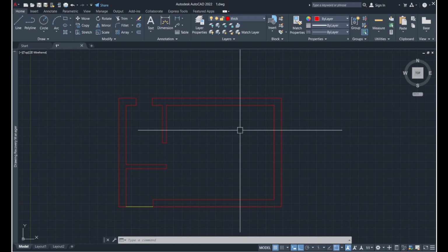The point being, it would depend on where your window sills and furniture projections could start. The reason I do it at 1 meter or 1.1 meter is that usually my sills are at 90 centimeters, so that the section plane could cut the windows and you could see the projection of all the furniture as well. So now let's go ahead and create the windows for our living space.